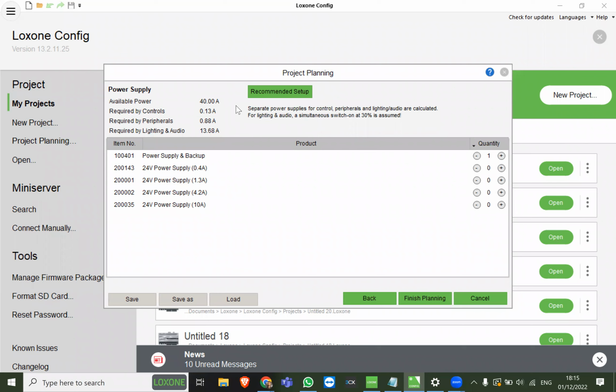So you have 7 outputs and you can fuse them to different levels. For example, if one output is going to all your peripherals, your presence sensors and touches, you don't need to have 10 amps on that circuit. You can limit it or fuse it to 2 amps. That way your devices are protected. And again, you don't need that many blade fuses in the panel, but I'll show you that as well.